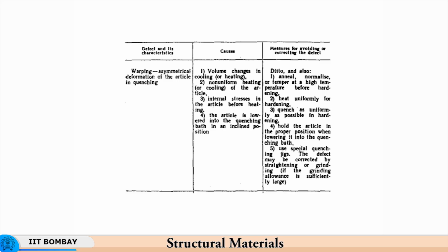So, effectively what is happening is you counter the change in shape due to the volumetric change that is taking place. Care has to be taken that the volumetric change should not result in introduction of too much residual stress in the material, as otherwise it can result in cracking. So the restriction provided by the jigs should be small, or to a reasonable extent, so that no cracking takes place.